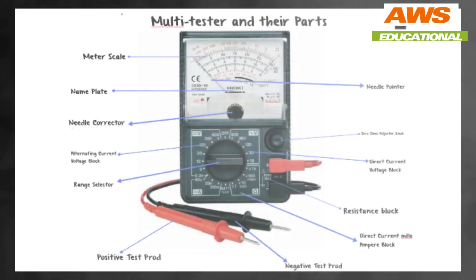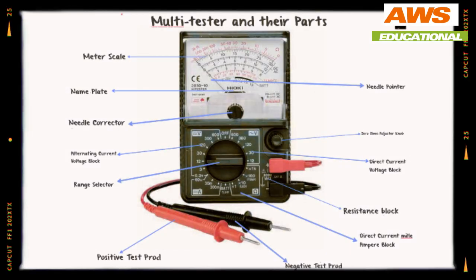Working of analog multimeter. Since the analog multimeter is a PMMC type instrument, when a current is passed through its coil, the coil moves in a magnetic field produced by the permanent magnet. A pointer is attached to the coil. When current flows in the coil, a deflecting torque acts on the coil that will rotate it by an angle, so the pointer moves over a scale. A pair of hairsprings is attached to the spindle to provide the controlling torque.